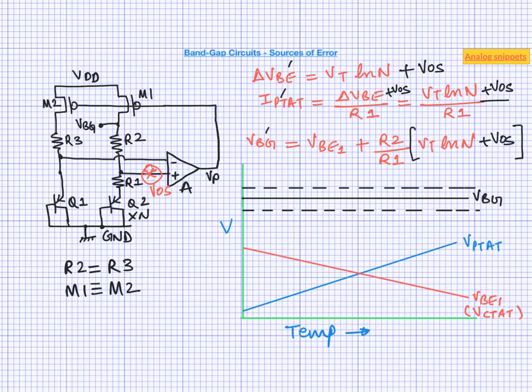Another circuit technique to basically entirely remove the mismatch in PMOS is to short these two nodes. By doing this, we essentially have one current source on the top of this resistor and BJT stack. Remember, the purpose of these PMOS was to maintain equal current in these two branches. In the modified design, this purpose is served by the resistor matching alone, and resistors are much better matched than the PMOSes. On the flip side, shorting these two nodes makes the bandgap startup much more difficult.